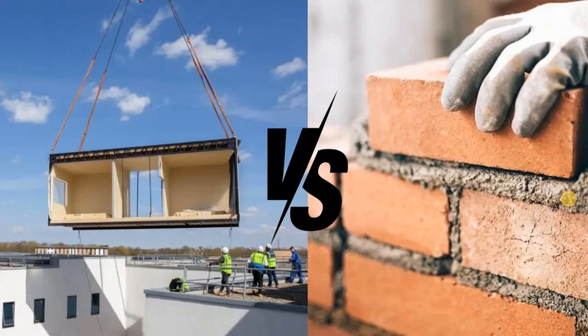So first let us discuss the difference. On the left hand side picture you can see the precast construction, and on the right hand side it is the cast in situ construction. The major difference is, if we talk about precast, each and every element is casted on site or in a factory depending upon the situation. So precast means elements are casted on the ground, in a shaded area or the factory, and then it is transported and erected at the site.